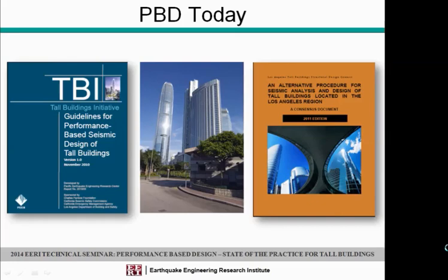These documents take, as Farzad will tell you in a few moments, the ASCE 41 methodology, and they extend it specifically for use in tall buildings. They are definitely about performance-based design to obtain equivalent performance to what you would get out of the building code. They're not about getting better performing buildings.